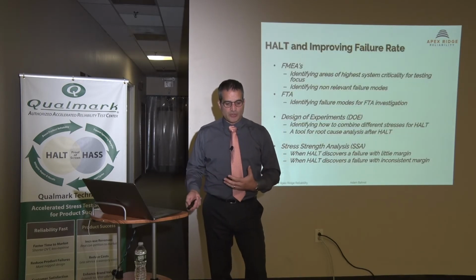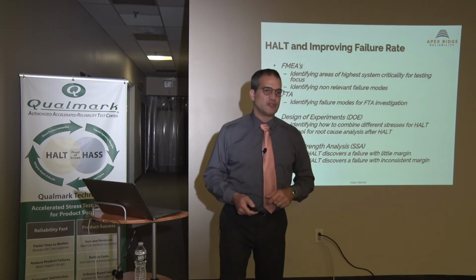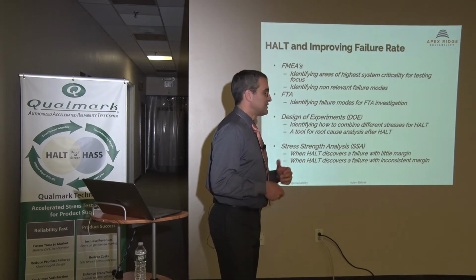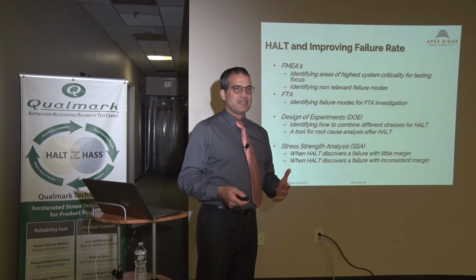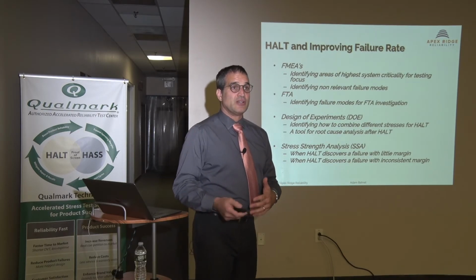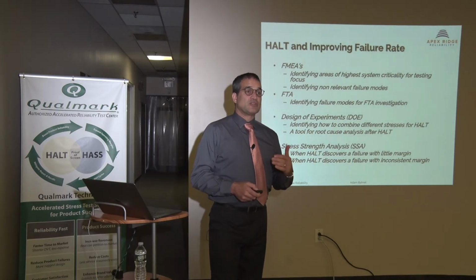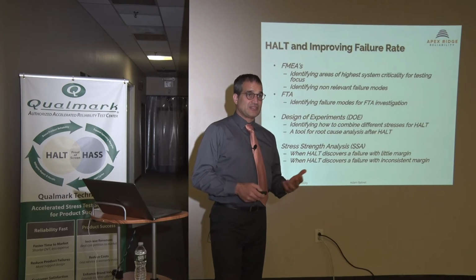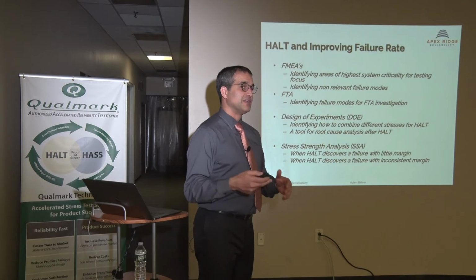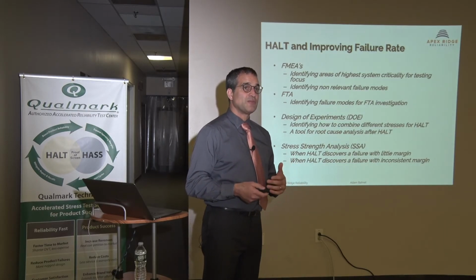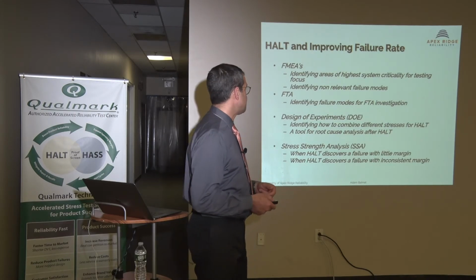So some of these other tools that it very commonly interacts with is FMEAs, failure mode effect analysis. The idea with an FMEA is to speculate as to all the types of failures that could occur, what drove it, what the effects are, and then to create actually a quantitative ranking system of severity, likelihood of occurrence, detectability, and rank these different failures. And then that will drive actions, and some of these actions might be HALT testing.